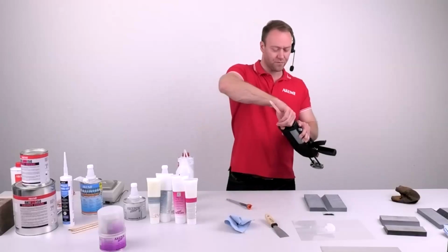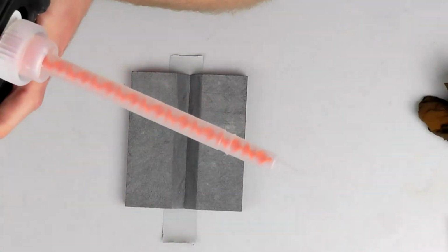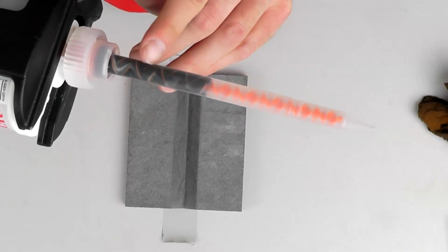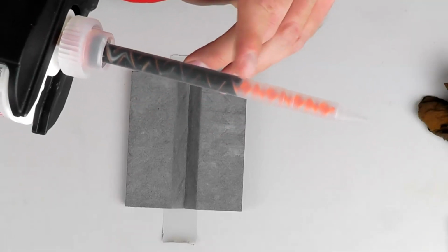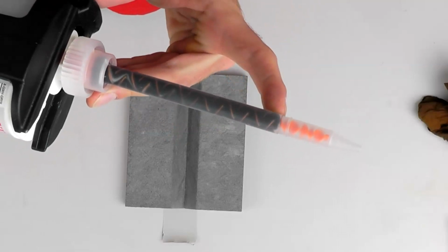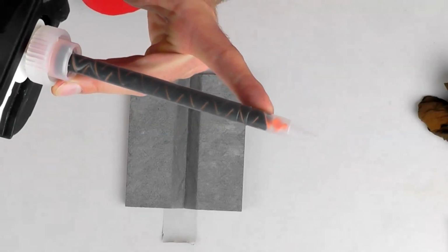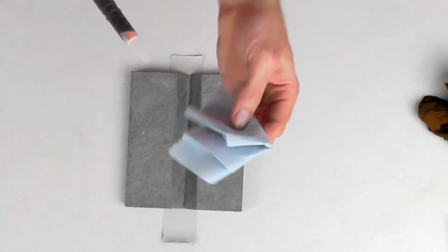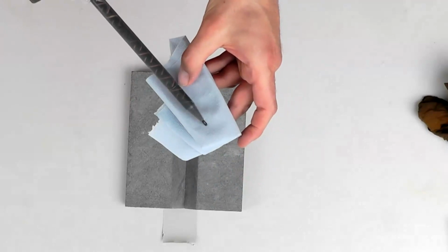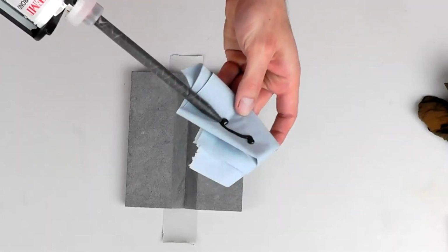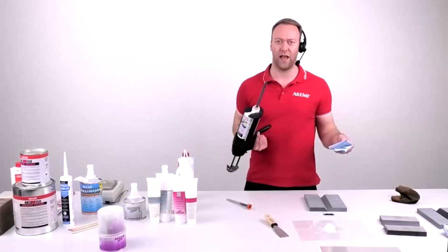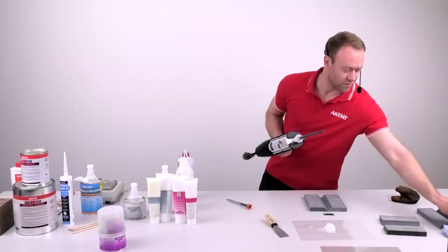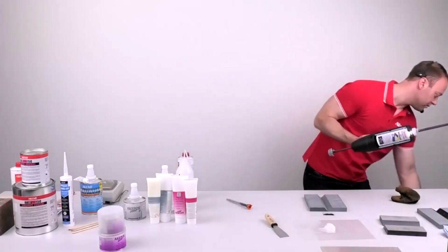And again here we press, and you can see the A and B. The white is the hardener, and it gets mixed. Here it is still visible. Here the mixing ratio is good already. It's all properly mixed, one homogeneous color, but still we want to be 100% sure. So we throw away 2-3 centimeters. First, we don't want any air bubbles, and second, we want a proper mixture. Good, let's throw that here.